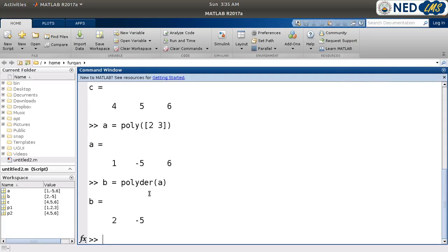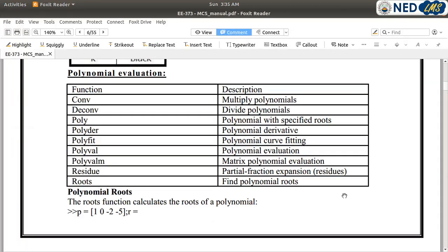And now going back towards the manual again, I think you guys can explore these functions on your own, as it is getting pretty basic. I am now describing this function as it is the important function. This function takes the inputs of a transfer function in the form of numerator and denominator polynomials, and returns three vectors R, P, K. Let me describe what these vectors are.